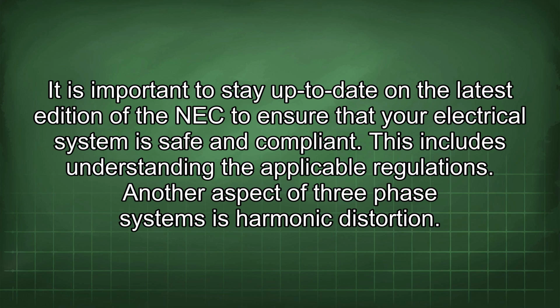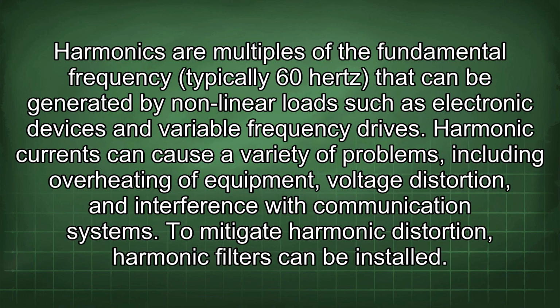Another aspect of three-phase systems is harmonic distortion. Harmonics are multiples of the fundamental frequency, typically 60 Hz, that can be generated by nonlinear loads such as electronic devices and variable frequency drives. Harmonic currents can cause a variety of problems, including overheating of equipment, voltage distortion, and interference with communication systems.